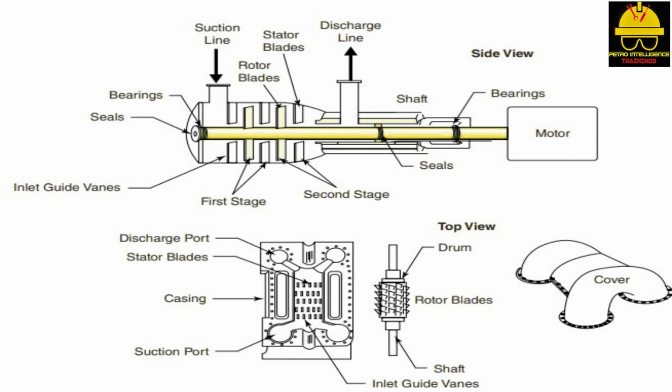Axial compressors are limited to approximately 16 stages because of temperature and equipment stress. Axial flow compressors are often used in series flow with centrifugal compressors because they are capable of operating at greater capacities. The primary application of axial compressors involves the transfer of clean gases such as air. The internal components of an axial flow compressor are extremely sensitive to corrosion, pitting, and deposits.